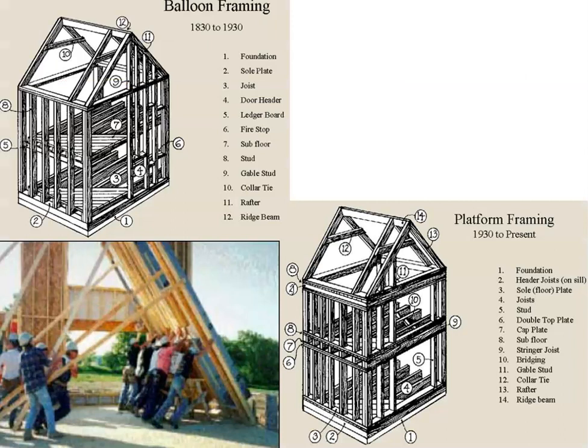So just briefly about framing. Wood framing has evolved over the years. From the early days, previous to balloon framing, it was heavy timber framing, really. Heavy timbers that were cut down really on the farm in the exact area pretty much where the building was built. That's how it all started. And then about 1830 or so is when the railroads started making their way across the United States. And that is when dimensional lumber from sawmills became available throughout the United States.